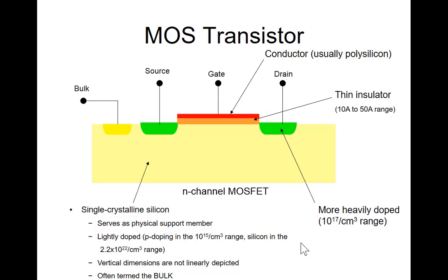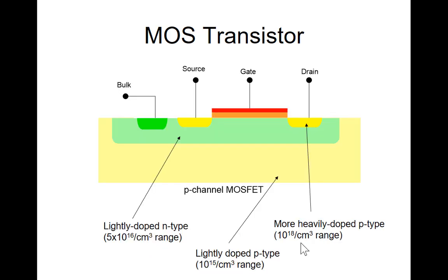And this page is showing the different doping levels of different areas. This talks about the source and drain area for NMOS transistors, and then the well doping, the P diffusion, the PMOS drain and source doping, and the substrate doping.